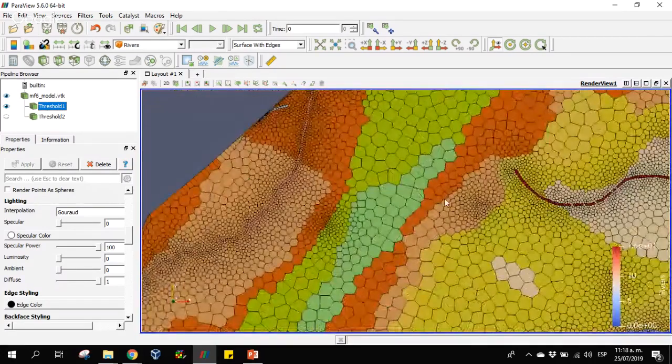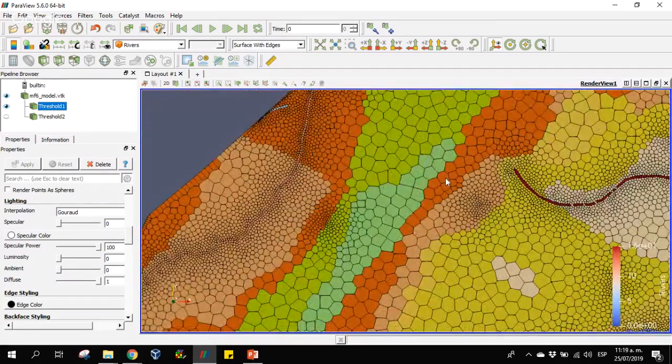The influence radius is equal to 700. So from the well, we create a radius of 700, and the cells of the model change in size from 300 to 40 over a distance of 700 meters. So this is the meaning of the influence radius.